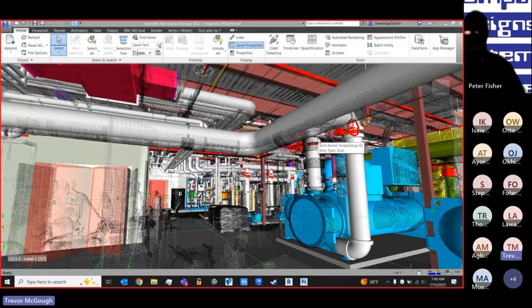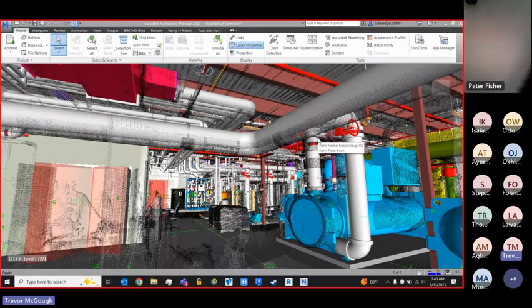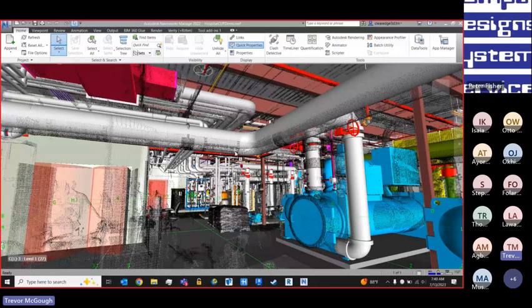So as the screen gets fired up, Verity is construction verification for Navisworks. The starting point is actually going to be inside of the Navisworks application. With that, we have two things loaded in. Number one, we have geometry. Number two, we have the point cloud data representing our as-built. With these two things loaded in, we'll begin our Verity workflow.